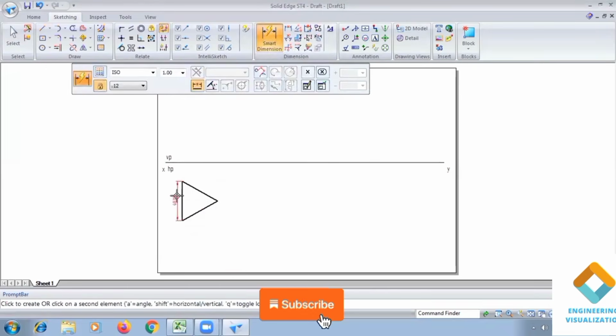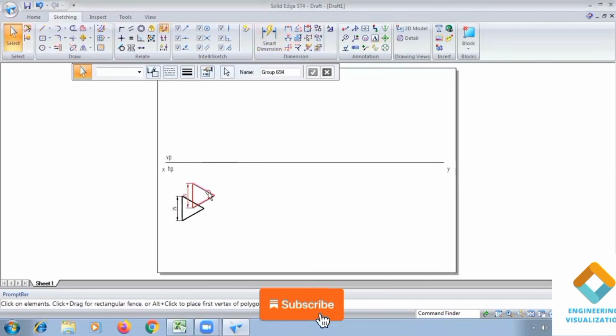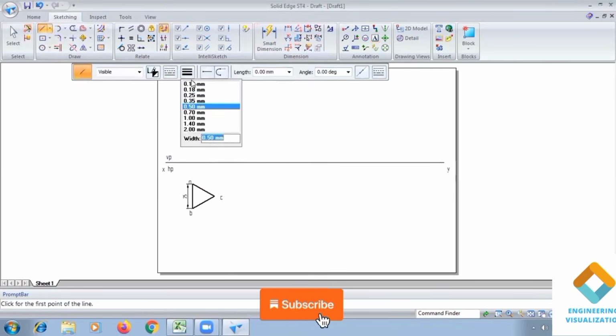Now go to smart dimension, select the vertical edge here, and give 25. I'm showing this problem with a dimension of 25. The same thing you can do in the exam for 50. Based on the question given, you need to do it. For showing purposes I'm doing it for 25, but the procedure will be the same. So draw the projection lines to complete the top view.